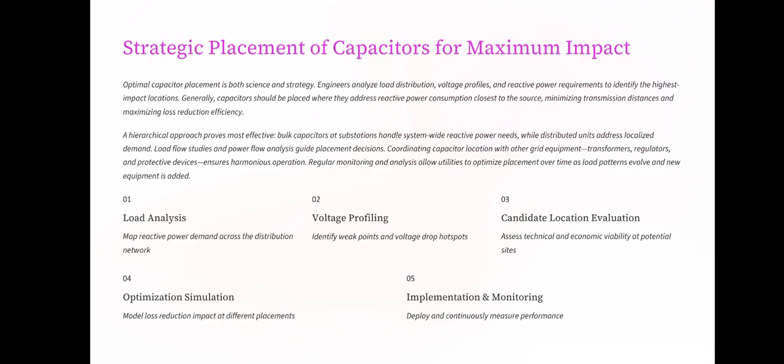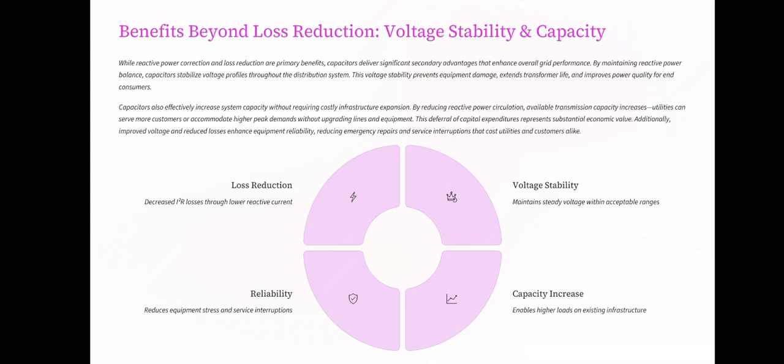Map reactive power demand across the distribution. Voltage profiling. Identify weak points and voltage drop hotspots. Candidate location evaluation. Assess technical and economic viability at potential sites. Optimization simulation. Model loss reduction impact at different placements. Implementation and monitoring. Deploy and continuously measure performance.